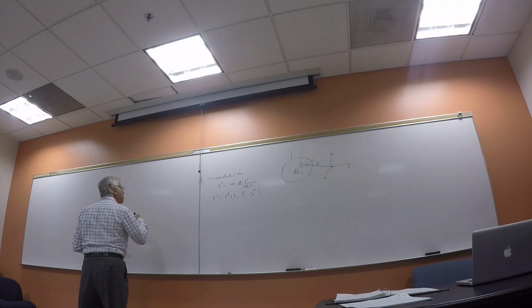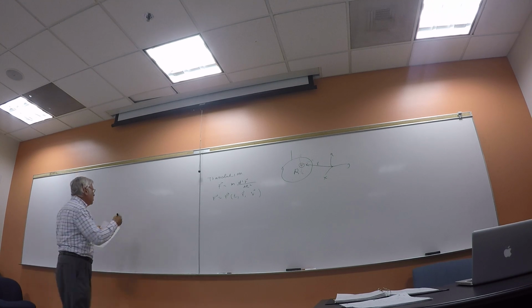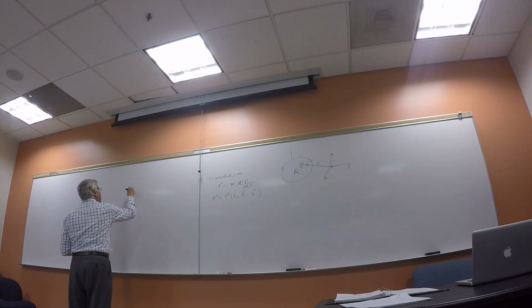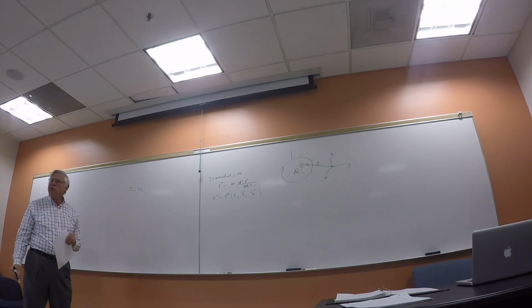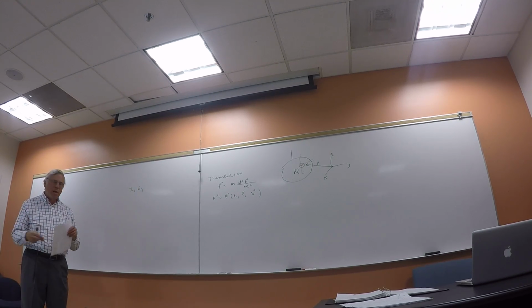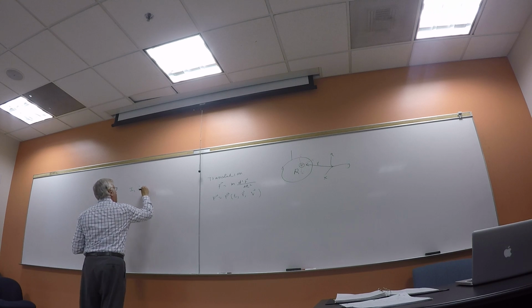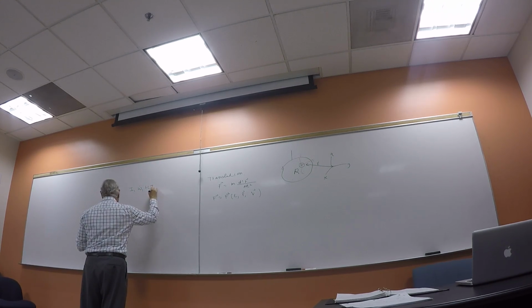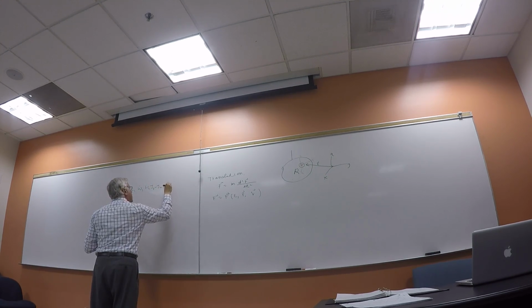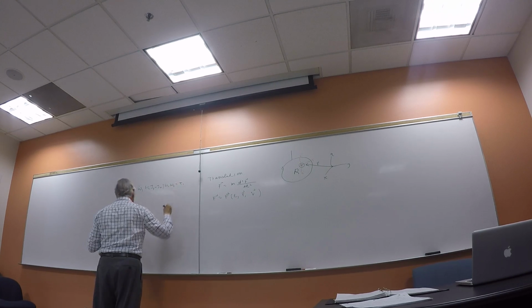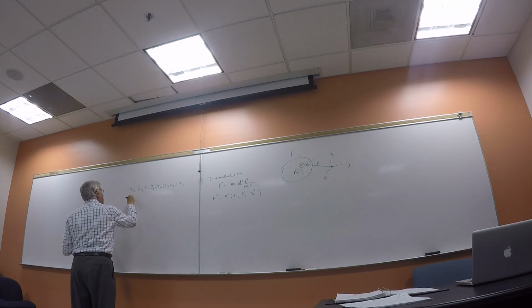And then the equations of motion are the famous Euler's equation. I'll just write them down. We're not going to solve them, just give you an idea. You have I1 omega 1 dot. Remember, that's a shorthand notation for the derivative of omega 1 with respect to time, plus, what do you have over here? You've got I3 minus I2, omega 2, omega 3, equals tau 1. I'll tell you what these symbols are in a second, okay?